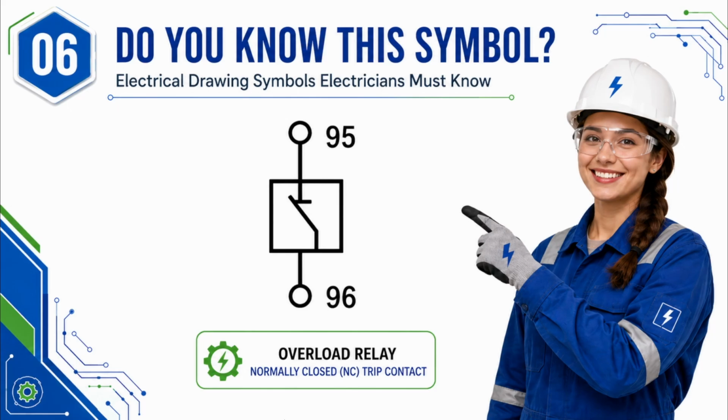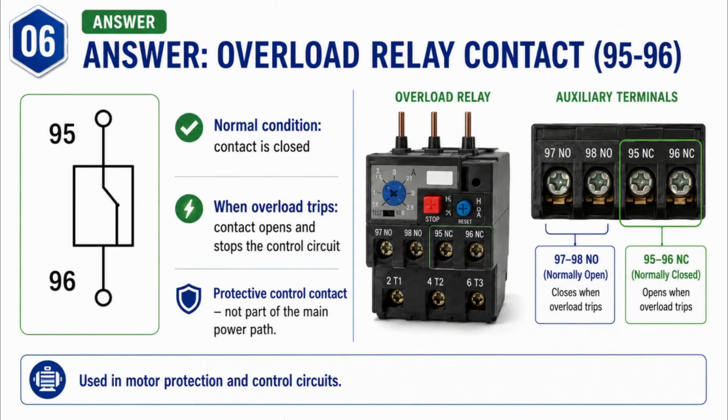You will often see this contact in motor protection and control circuits. Can you identify it? Let's check the answer. The answer is the overload relay normally closed contact, terminals 95 and 96.